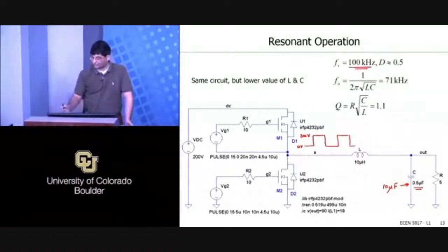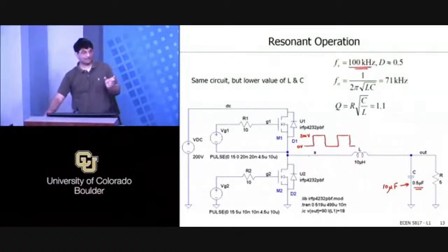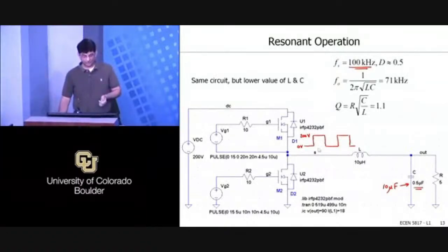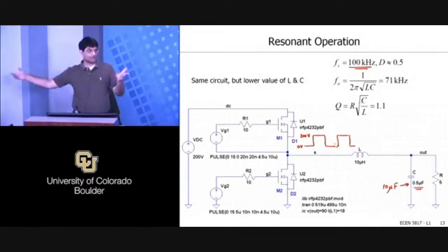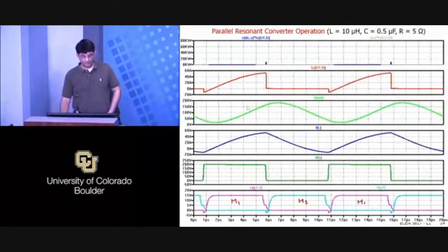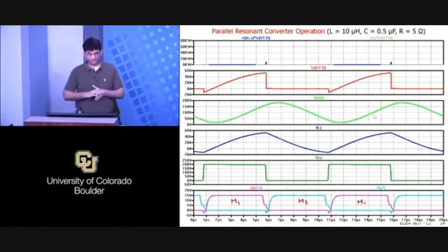And if you put it in a resonant tank which has a resonance frequency close to the switching frequency, it's going to keep that fundamental and attenuate away the higher harmonics. So it's going to basically take the square wave, keep its fundamental, and smooth it out, essentially. And that's what you're seeing, right? A smoothed out version of that square wave, but the average value is still 100 volts, right? Makes sense.